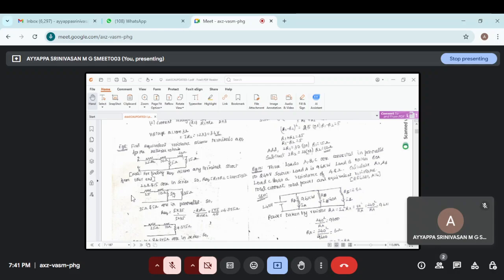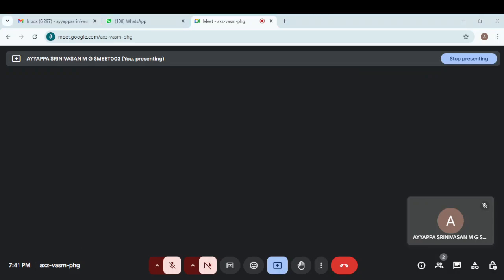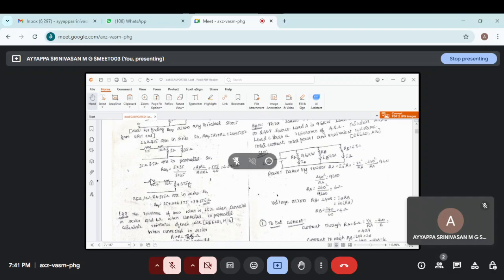4.375 ohm. This is what? The reduction of 35 and 5. So, we have reduced this in this way. Now, consider 25, 10, 4.375. If you see, if a voltage source is connected across this terminal, then through 25, 10, 4.375, the same current will be flowing through them. So, we have to add, which will give 39.375 ohm. This is the answer.